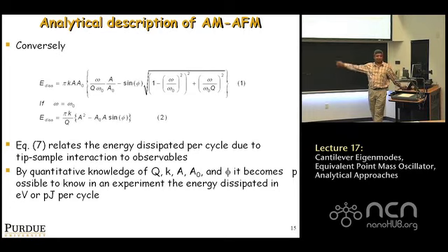These are really small numbers for mechanical energy losses. Yeah. So the dissipation is given by, because I am breaking like a bond. What is that dissipation? Where does it come from? Yeah. It's a bond that I am breaking. Yeah, so yes, the dissipation, well, it depends on the sample. In some cases, if you're doing it on polymers, it could also be some viscoelastic. In the small interactions, you're making chains slide relative to each other. Mostly, though, it is actually hysteretic interactions due to either water meniscus making and breaking or due to tip atoms assembling and ripping apart.